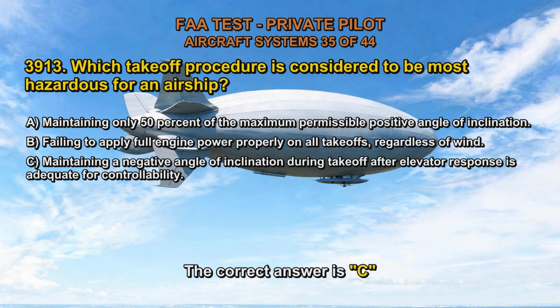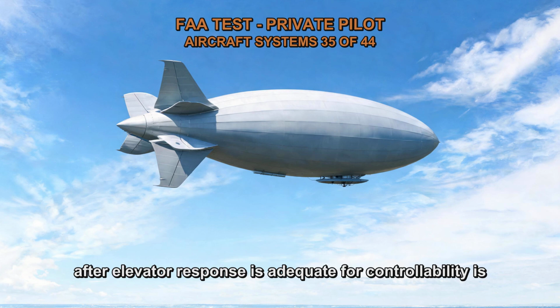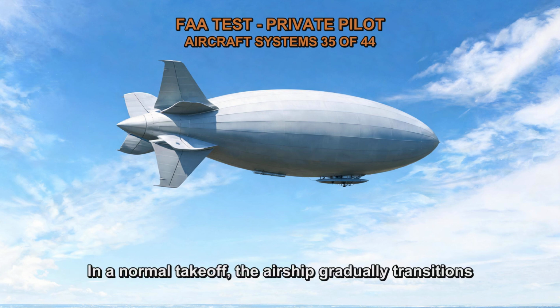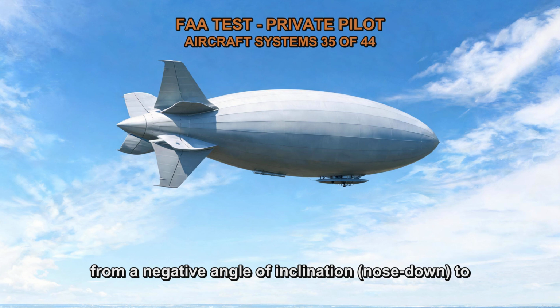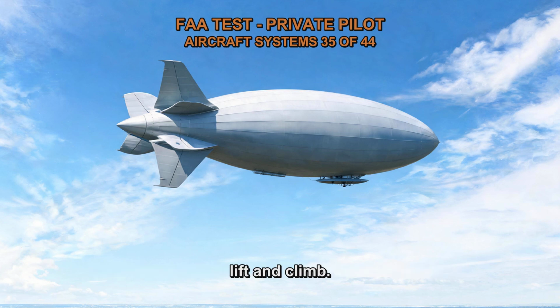The correct answer is C. Maintaining a negative angle of inclination during takeoff after elevator response is adequate for controllability is considered the most hazardous takeoff procedure for an airship. In a normal takeoff, the airship gradually transitions from a negative angle of inclination, nose down, to a positive angle of inclination, nose up, to achieve lift and climb.